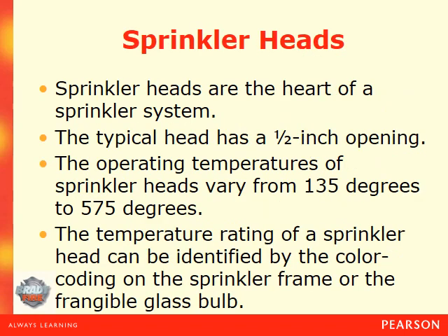The sprinkler heads are the heart of the sprinkler system. The typical head has a half-inch opening. The operating temperatures of sprinkler heads vary from 135 degrees to 575 degrees. The temperature rating of a sprinkler head can be identified by the color coding on the sprinkler frame or by the frangible glass bulb.